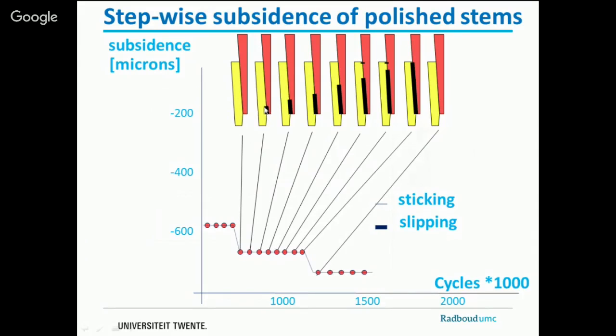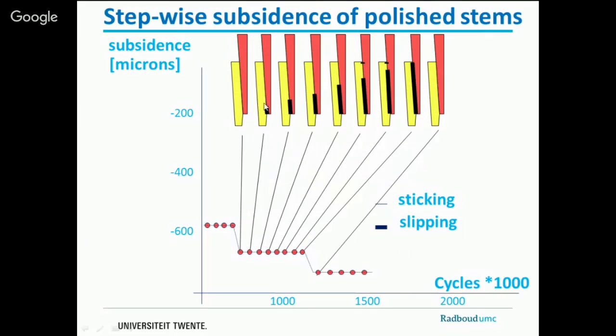Subsequently, we have high stresses here in the cement at the tip, and we include creep. Due to the high stresses, the cement, let's say, goes away, and at the tip we see movement, we see slip every time. And because it's slipping there, high stresses go up here. Because of the creep, the slipping part is going to increase. So first we have slip at the tip,